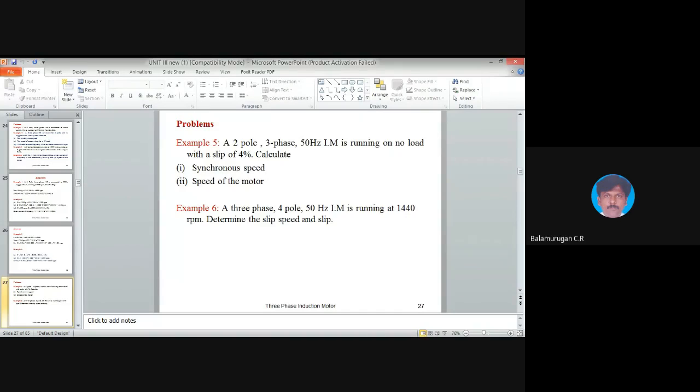redraw this diagram. So phi x is 0, which means this phase will not be available. The remaining two phases will be available. We do not need to draw this segment, because here the value of phi x is 0. So we will have only phi z and phi y, and this angle should be 120 degree.